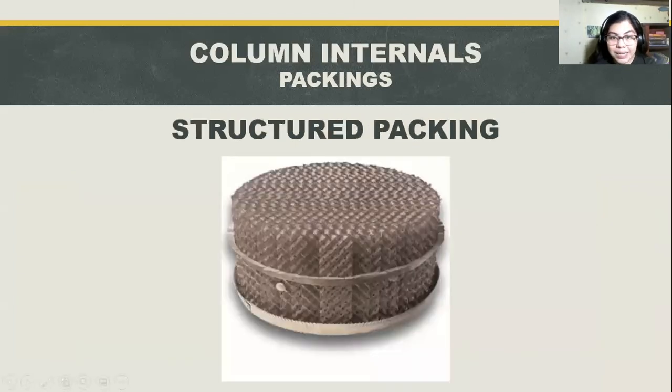Lastly, we have here structured packing. Structured packing is an organized packing, and it is usually used to channel liquid material into specific shapes. Materials used here are usually metals, plastics, and porcelain, and we have to consider that their internal structures must be arranged into different honeycomb shapes. Structured packings are designed in order to provide a large surface area for liquid to contact without causing resistance that impedes the liquid flow.